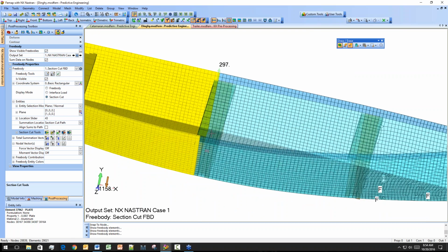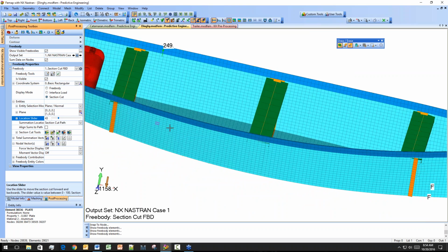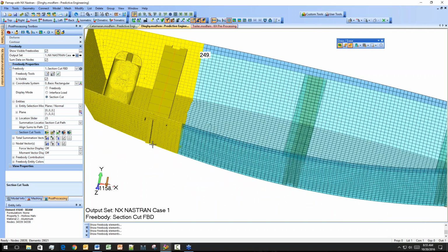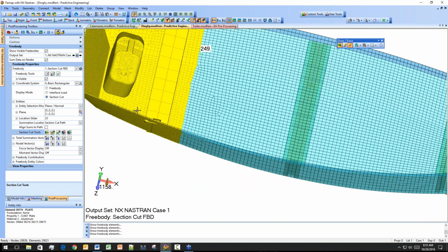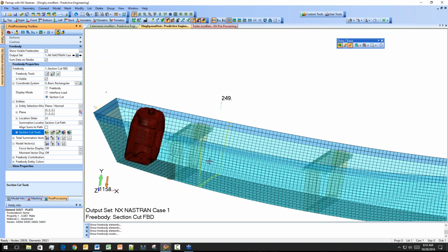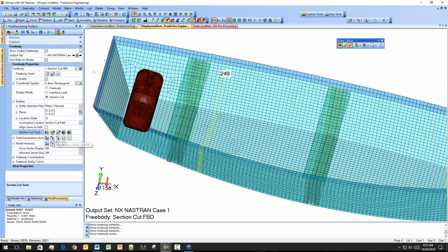We've got a nice clean mesh of this direct line that the plane is cutting across. But if we move back to the other area of the boat, it's not necessarily a straight line that it's selecting. And so you might get some funny forces based on where or what the elements look like that you're chopping at. So just be aware of that. And you can also see the nodes that it's selecting. So it's grabbing the nodes right around where that plane is at on the edge of those elements.